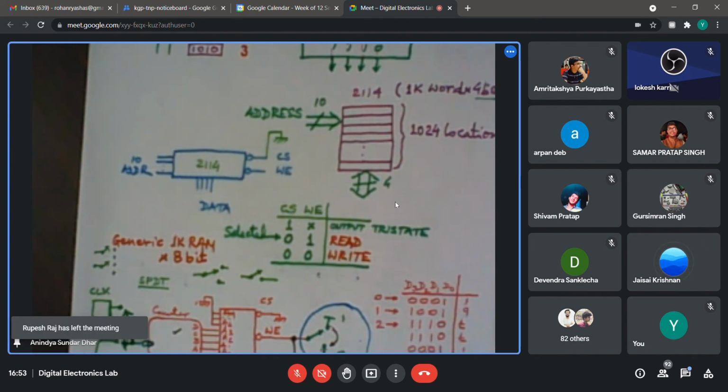By number. So there you won't get the RAM. You need to go to the other one, digital by function. There you will find a sub menu called minor device class or something, and there you will find RAM. If you choose that, there are two devices coming. One will be some CMOS series 4505, I think. The other one is simply said RAM 1K. It won't give you any number like 2114. It is not 2114 anyway, but 2114 is 4-bit wide, and this is 8-bit wide.